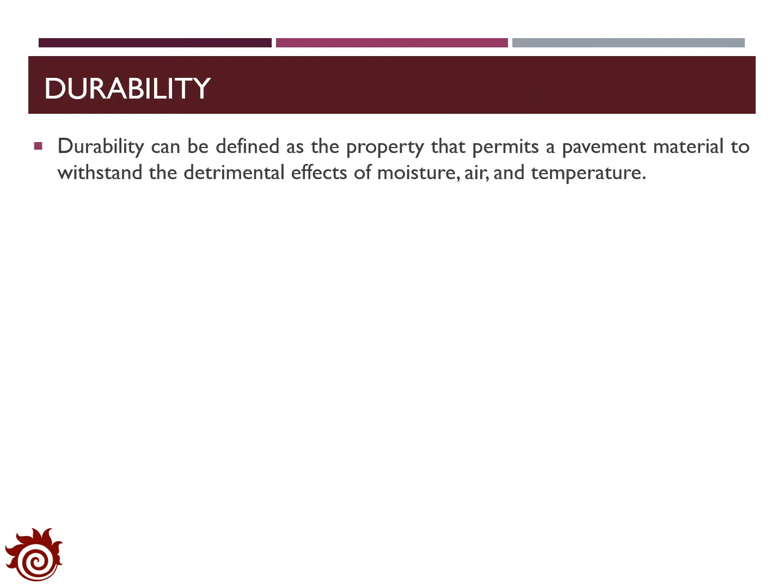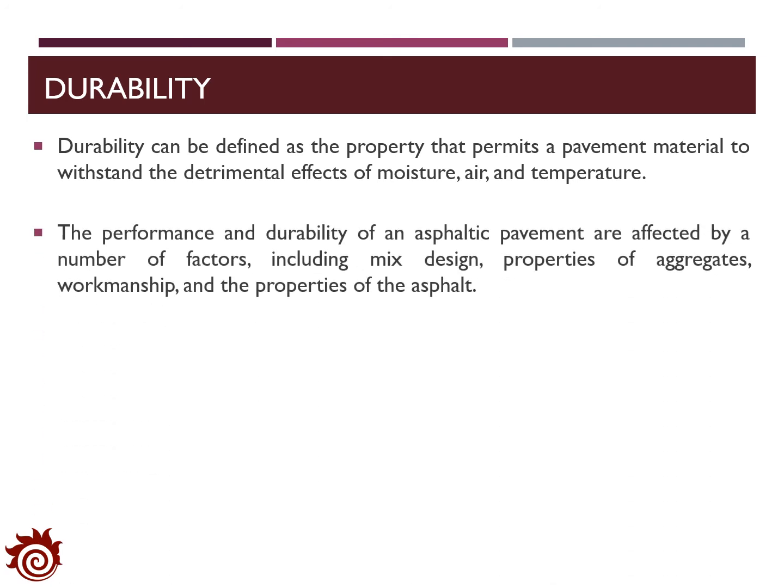The last property of asphalt cement we want to introduce is durability. Generally, durability is defined as the property that permits the pavement materials to withstand the detrimental effects of moisture, air, and temperature. Usually, the performance and durability of the asphalt pavement are affected by a number of factors such as mix design, properties of aggregates, workmanship, and the properties of the asphalt.